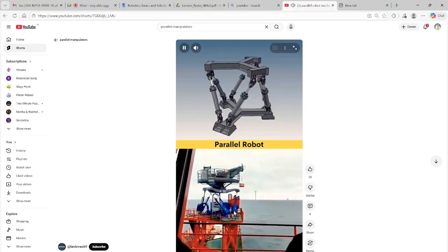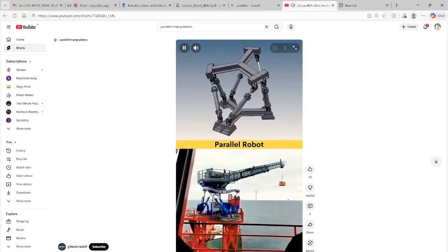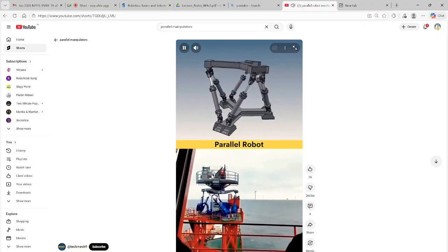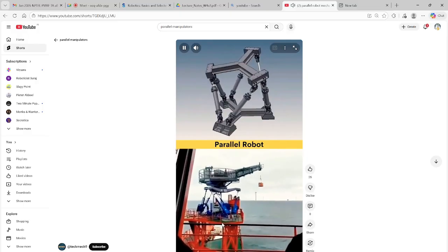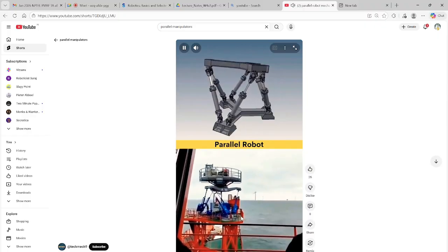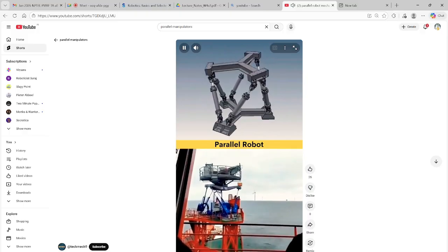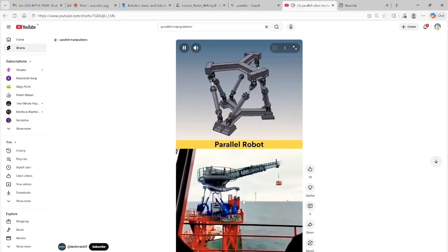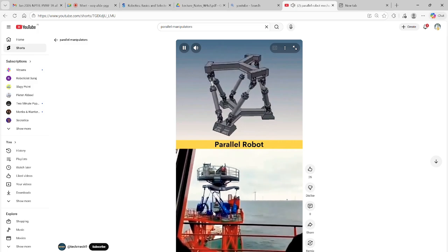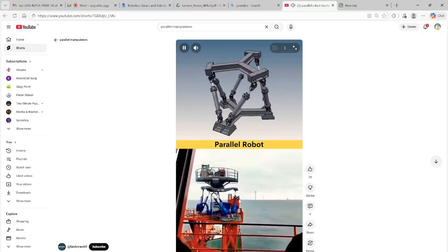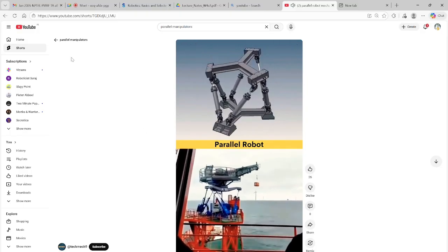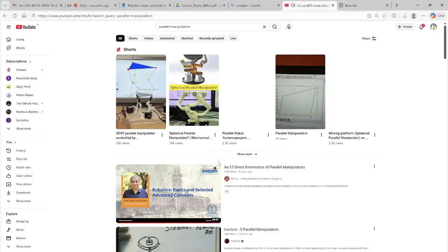You see the base is fixed, and then linkages are there between both of them. There is a revolute joint standing on top of the base, which moves it in different directions, and all these links are controlling the mobile base of the robot. So this is an example of a parallel manipulator. You might see it is not serial, it is parallel. Why parallel? Not because the links are in parallel, but because all those links connect the mobile base and the fixed base, right.